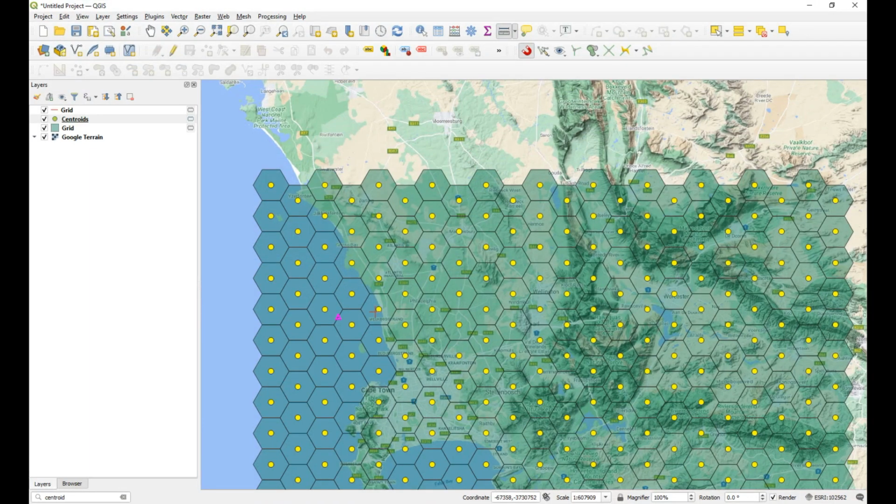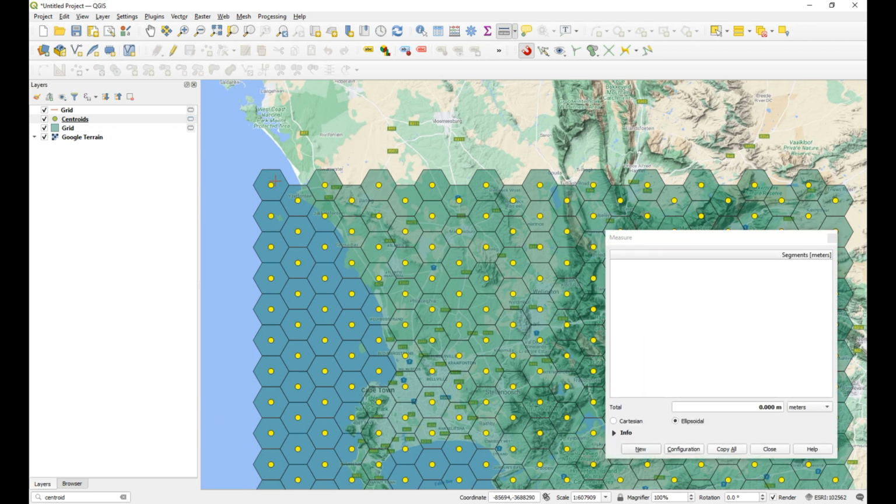And if we go back to QGIS, when we ran through this little measurement, we saw that the closer we got to our point of contact, which for LO19 is PAL, where we're almost in line with PAL now, it gets to 8660.250 from a much smaller value, and then starts changing again. That's the reason that happens. It's a long-winded way of explaining that, but sometimes these are important things to know. Then it gets smaller again. So point of tangency, least amount of distortion.